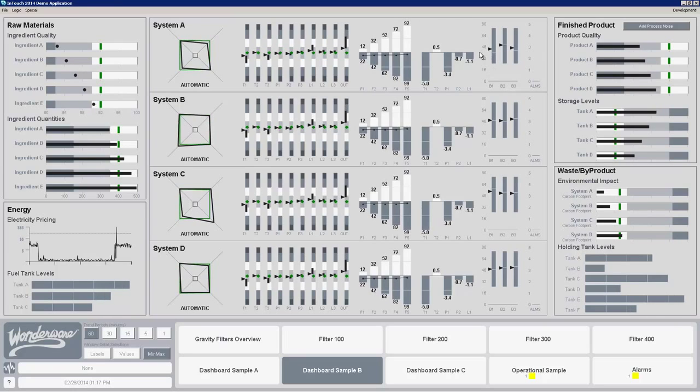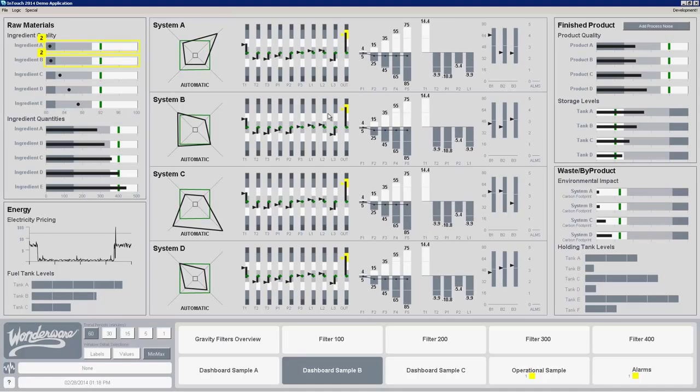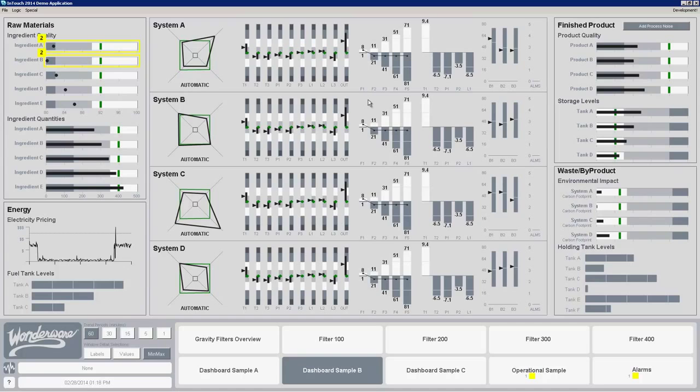This section here on the end is showing if there is an alarm. So if there are alarms, this would be basically a stacked column chart, which would show me the distribution of the different alarms by severity in those sections of the plant, so that I can go and address them. But the key thing I would want to know in this center section is generally, am I running well? Is my process available?